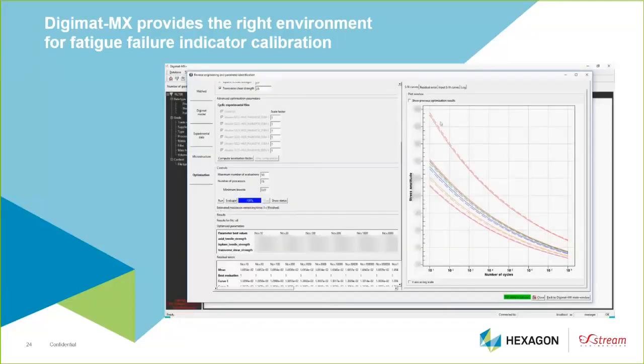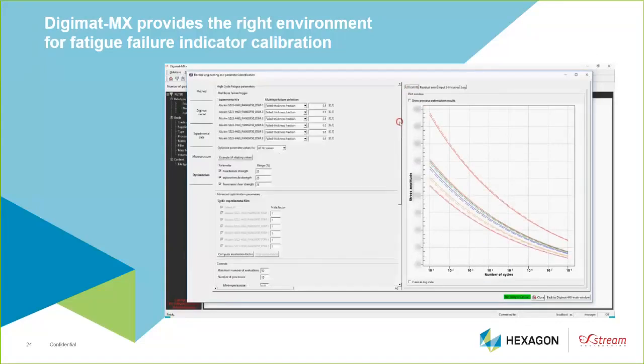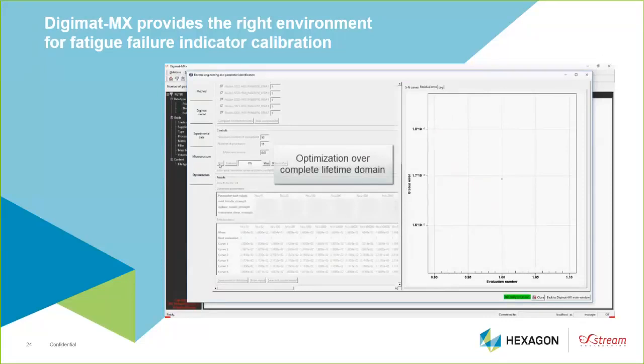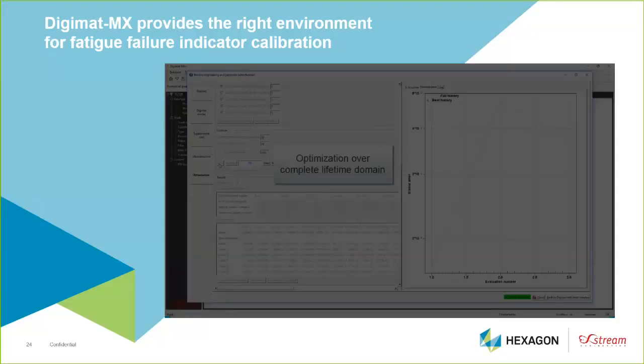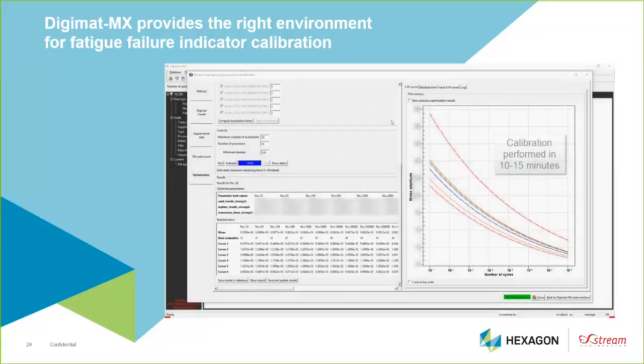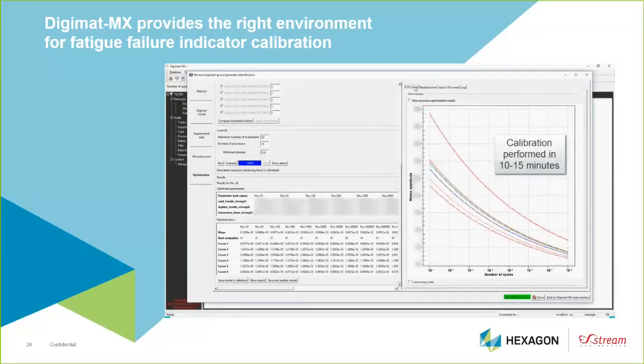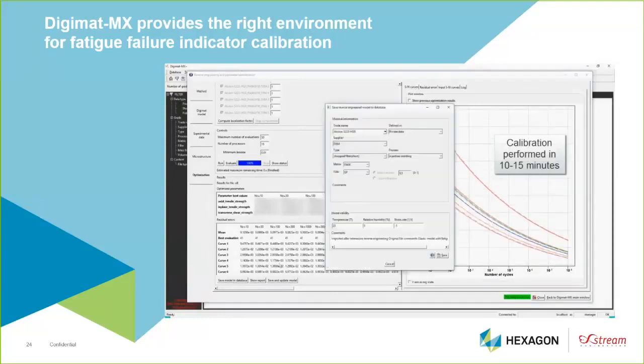That's what it gives. As you've seen, we only calibrated once and propagated the trend, so it's already giving you a very good fit all over the domain. So it's pretty straightforward: you calibrate once and propagate. And if you're picky, you can then optimize globally each point in order to have a much better fit for all lifetimes. You can see the parameter trends. And then when you save this model, as I mentioned, you can see that it presents the load ratio.